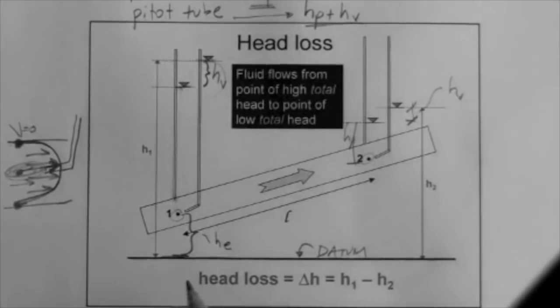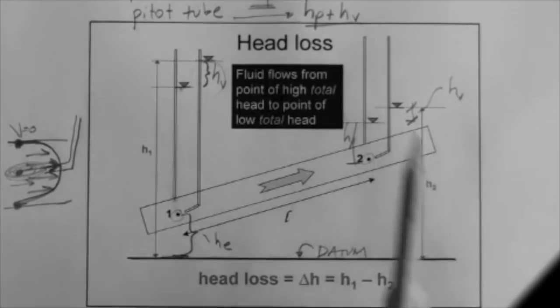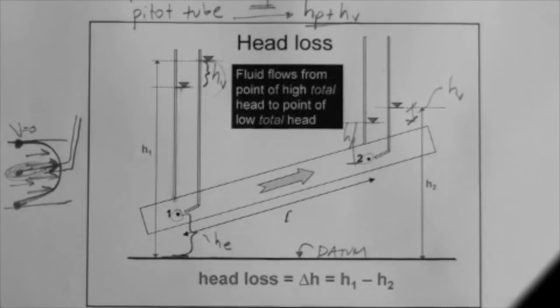But generally, we have some system below, or some boundary. In this case, let's say this is the floor or something, or just a line that is below these 2 points, and below the system, and that's what we call the datum. Okay, so again, please don't be confused in thinking that you have to select the same datum that I selected. You can select any datum you want, as long as you make sure that every distance you measure is with reference to that datum. Okay, in this case I selected this one, this line.